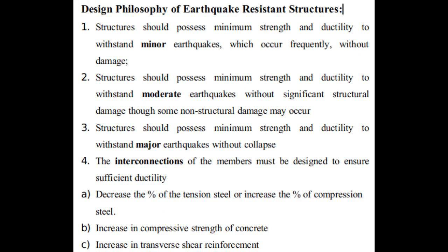Let us now discuss the design philosophy of the earthquake resistant structure. First of all, the structure should possess minimum strength and ductility to withstand minor earthquakes which occur frequently without damage. Number 2, the structure should possess minimum strength and ductility to withstand moderate earthquakes without significant structural damage, though some non-structural damage may occur. Number 3, the structure should possess minimum strength and ductility to withstand major earthquakes without collapse.